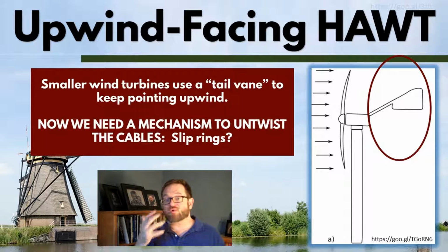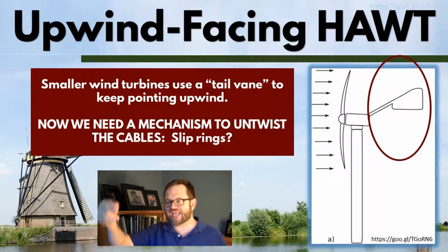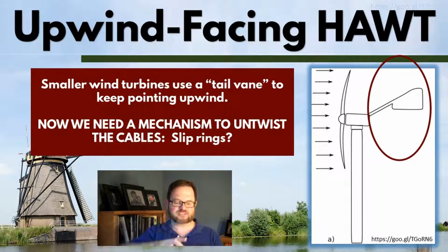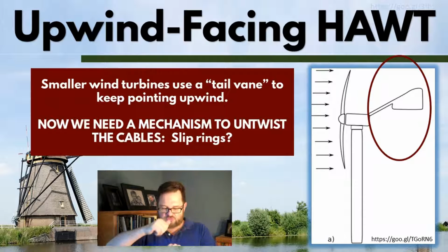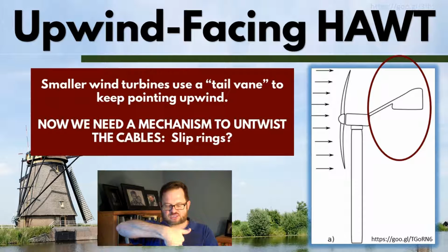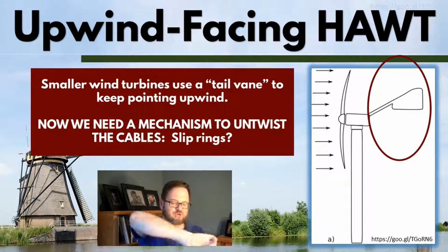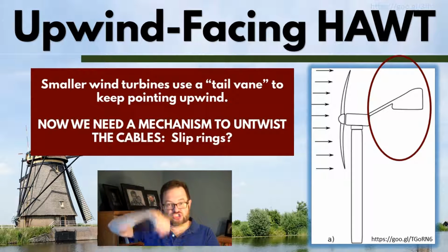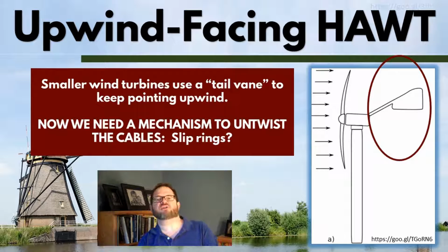Now, one way around it is to just not use cables to transfer the power down to the ground. Use what's called a slip ring, where two metallic rings are touching each other, and as the nacelle turns, the rings stay in contact with each other, and the electricity being produced by the generator will just flow through those rings and then to cables that take it down to the ground.